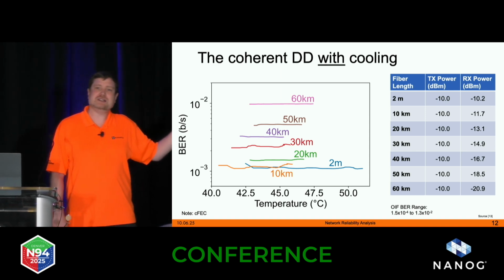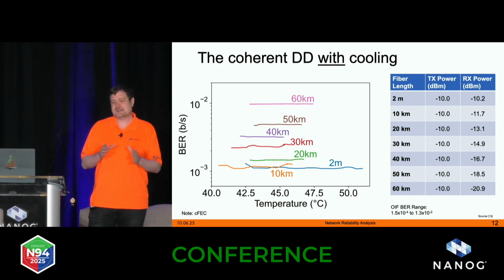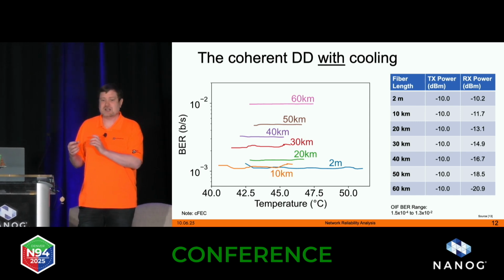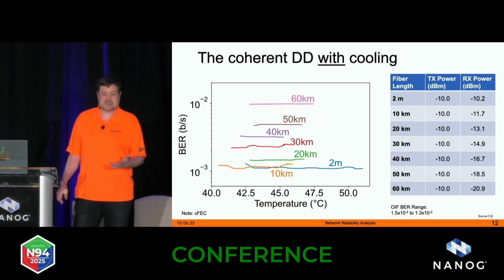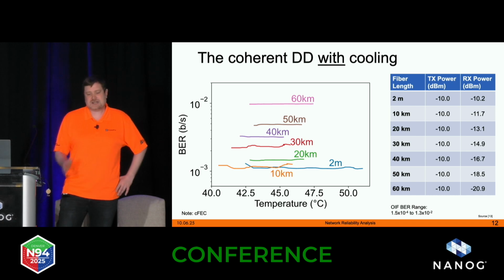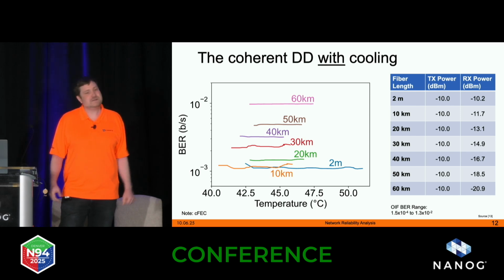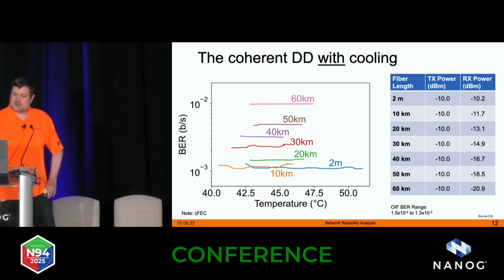Before we get to the interesting experiments, I want to show the diagram version with a coherent transceiver, so it goes well with the first picture we showed. And you can see quite a difference now, because the advantage of the coherent transceiver is that it benefits from more properties of light, meaning that the recovery is way better, but you also are dealing with higher temperature. But that is normal, and as you can see in this diagram, the advantage is you don't have any strange jumps compared to the direct detection one we showed previously. So the correlation with temperature is not really noticeable. The only correlation that is left is the length of the cable, basically. And it's also a different range because the specification of the coherent is also a little bit different.